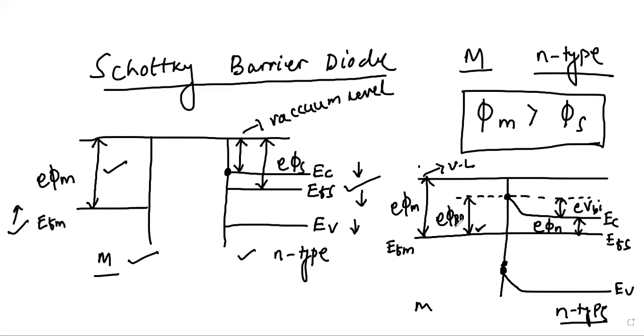Now you see how we can write what phi B0 depends on. So here, if you see this phi B0 barrier height, we can write this as, let me highlight this, phi m here, and then one thing, this E chi remains the same. This chi is the electron affinity, E chi. It is independent of the doping level.